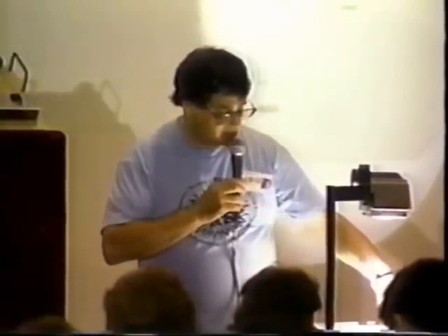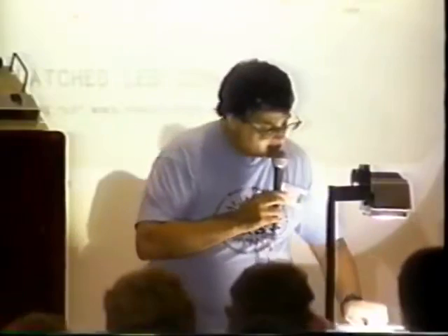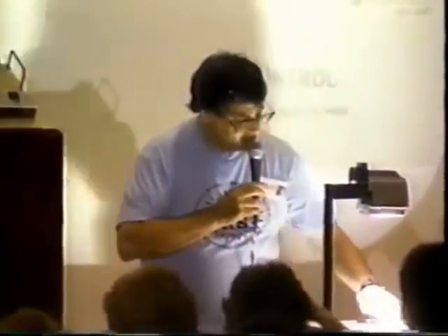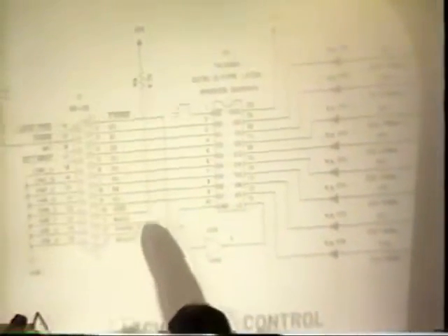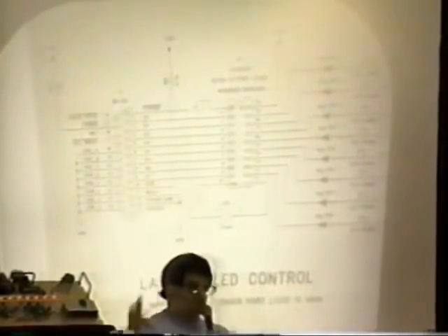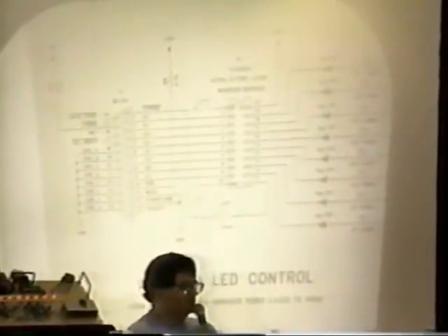What I did, sir, was to, you see this little resistor here? And there's another one, I think, somewhere. This acknowledge pin, I'm sorry, it's over here. Here's the other resistor. These resistors cost about 2 cents. And I connected these 2 lines to ground. And by doing that, the computer thinks it's talking to a printer. You need to add 2 little resistors, and 2 wires are shorted to ground. And at that point, when you say LPrint, the computer thinks it's online and it has paper and there's no errors and all those lines are correct.